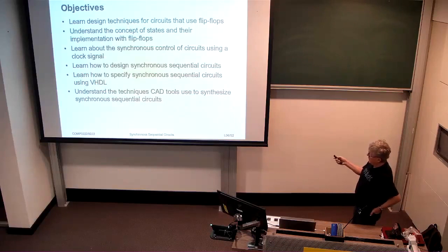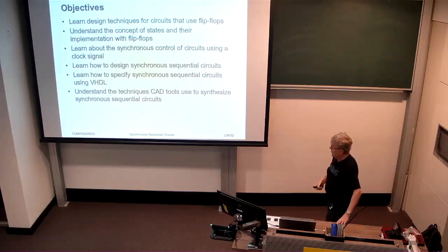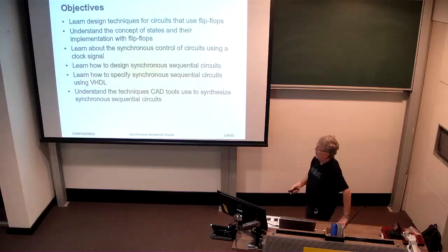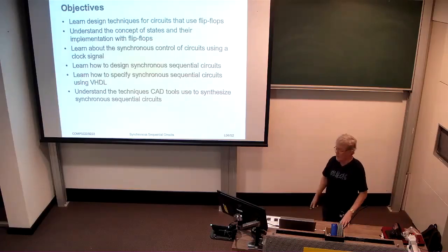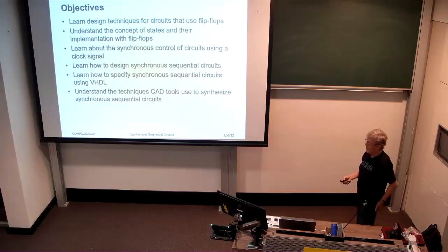We're going to learn about the synchronous control of circuits using a clock signal and hence the synchronous sequential circuits. We'll learn how to design synchronous sequential circuits, learn how to specify them using VHDL, and understand the techniques that CAD tools use to synthesize synchronous sequential circuits.